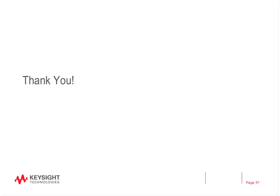Okay, thanks, Riyadh. Here's another question. What is the effect of spurs on filtering and isolation? So usually with filtering, the idea of filtering is to minimize those spurs, right? Depending on your filtering choice, you either choose a slow roll-off filter or a high Q sharp roll-off filter. Both of them have trade-offs in terms of passband response. In some cases you want to maintain the group delay signal quality of your transmitter, and so you can't go with a high Q filter. So the trade-off there is if you have spurs that are too close to your filter skirt or inside your channel or on the filter skirt, you end up having a larger spur than you originally planned for potentially, or what your system can tolerate.